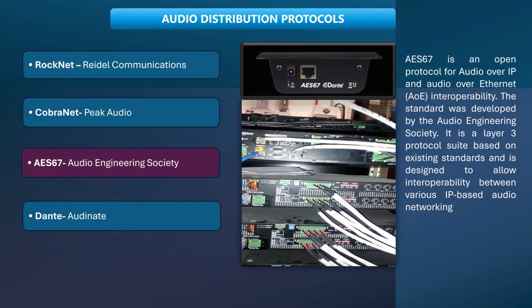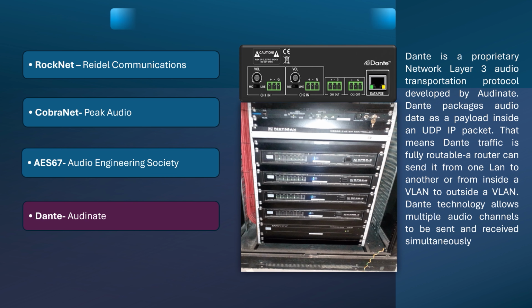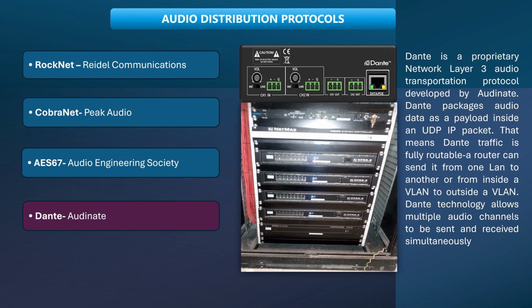AES67. AES67 is an open protocol for audio over IP and audio over Ethernet, AoE, interoperability. The standard was developed by the Audio Engineering Society. It is a Layer 3 protocol suite based on existing standards and is designed to allow interoperability between various IP-based audio networking. Dante. Dante is a proprietary network Layer 3 audio transportation protocol developed by Audinate.